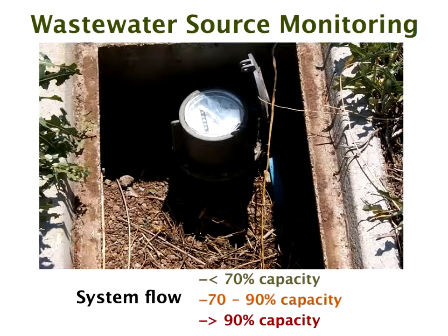Now, again, if it's a large number of homes, you're not going to get surges. It should stay fairly steady, and it should be okay. But if it does go up, you don't have that safety factor to handle it. But it's very important for the maintenance person to check the actual water consumption through the system per day against the design.